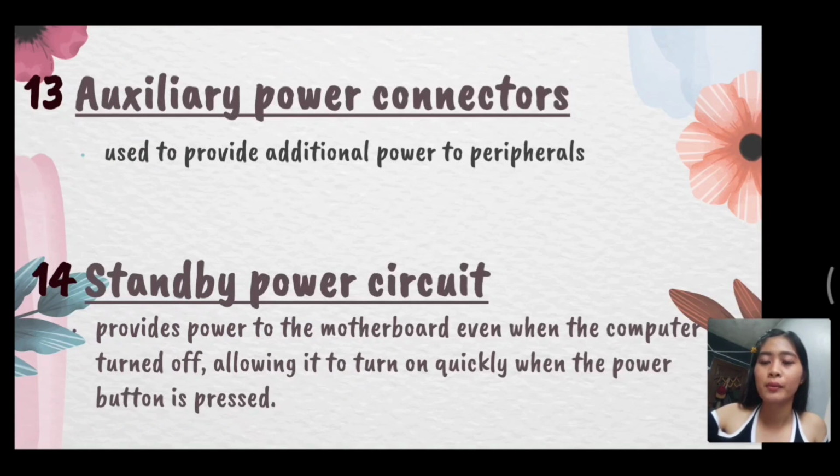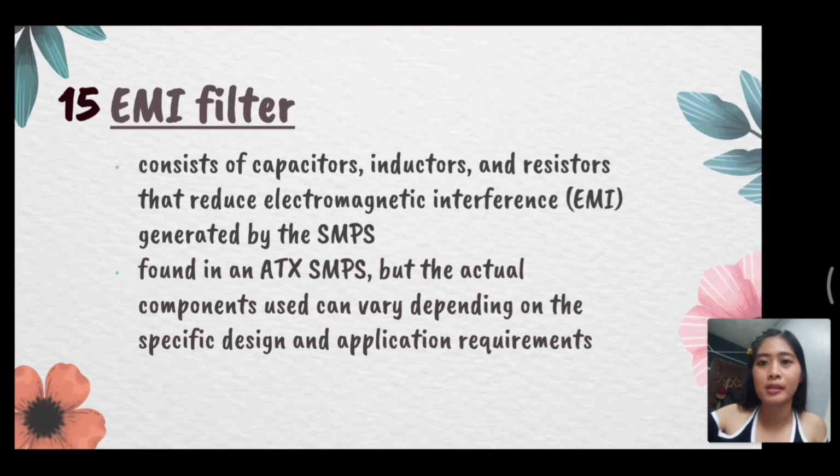Auxiliary power connectors are used to provide additional power. Standby power circuit provides power to the motherboard even if the computer is turned off. EMI filter consists of capacitors, inductors, and resistors that reduce electromagnetic interference generated by the SMPS.